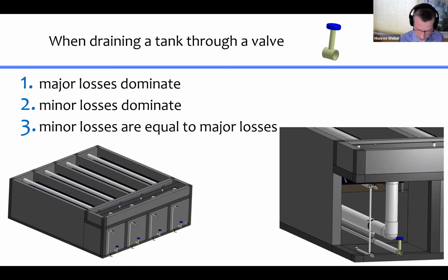If we look at the two equations for minor loss and major loss, they're so similar. There's major loss, there's minor loss. So what are we actually comparing? Given that the velocities are the same in both of them, we're just comparing which is bigger, FL over D or KE. If you knew which one was bigger, you know which one dominates. And then the question is, what's KE?